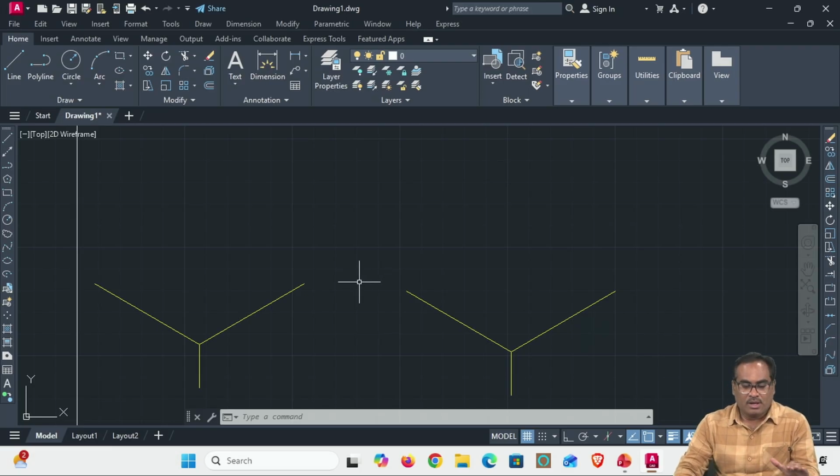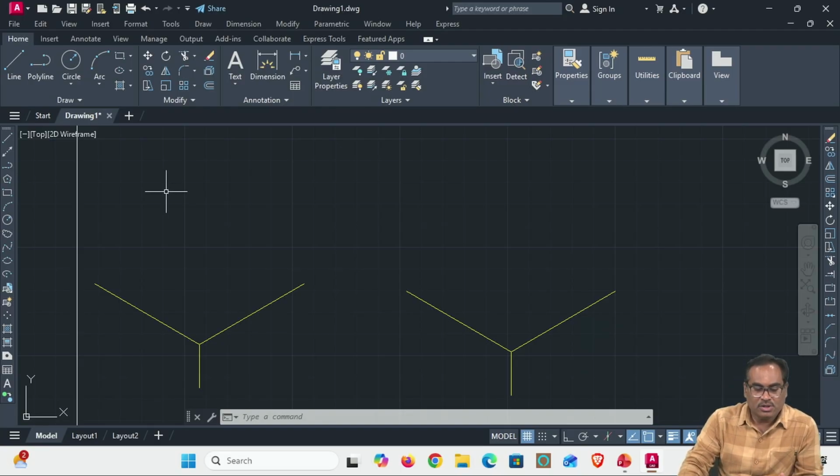First, the square prism with its axis vertical is given, right? So if it is given vertical, what we are supposed to do is, both sides of the base should be along two of the isometric axes, like that you have to draw. Okay, so I'll show you. If I explain, you will get confused. If I show you, it will be easy for you to see how I am drawing the base of the square. First I should draw the base of the square, right?